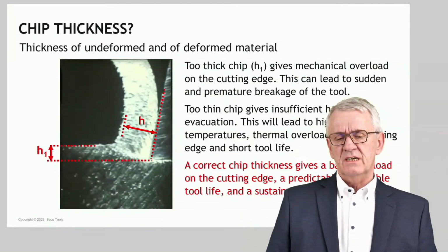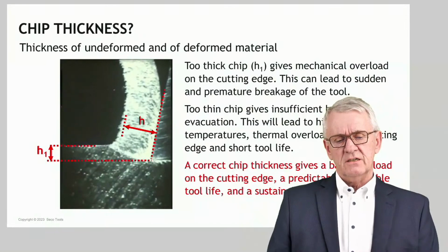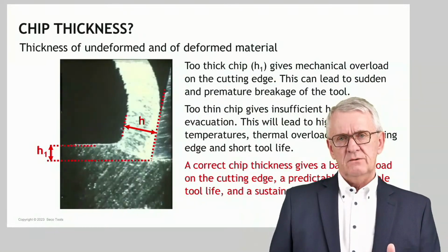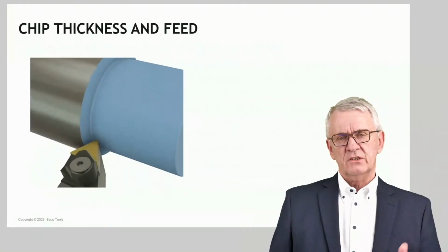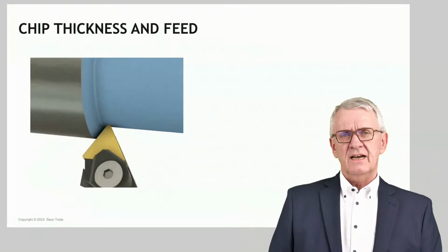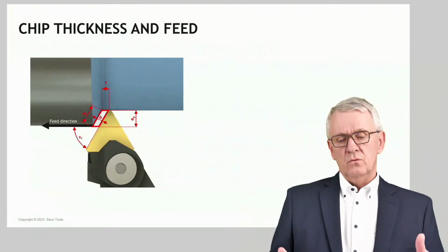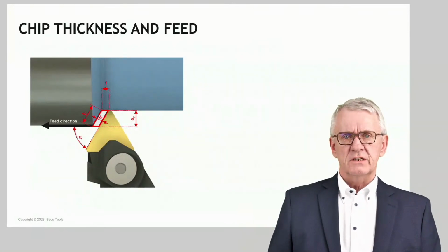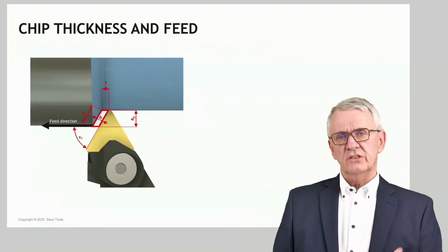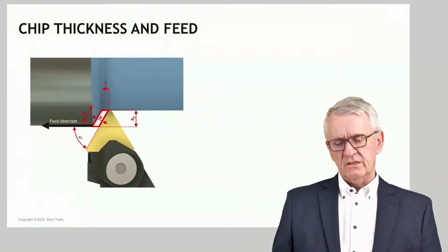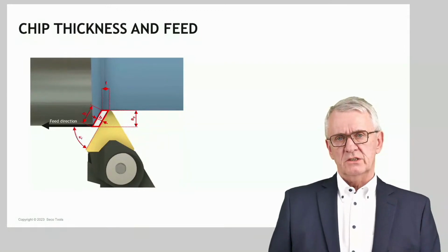And it's important to realize that, because now I have to ask all of you to take perhaps a very serious step, and that is that we have to be aware from now on that if we talk about cutting conditions in machining, there are kind of two levels we should talk about. One way of talking about cutting conditions is to talk about feeds and depths of cut and cutting speeds. Those cutting conditions very often are referred to as the workshop cutting conditions.